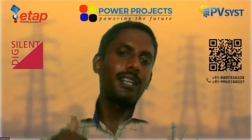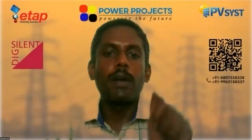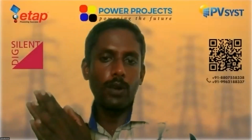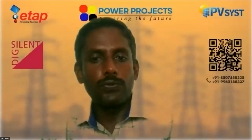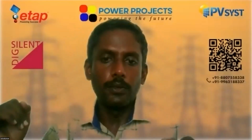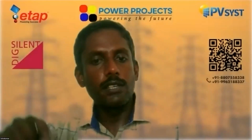If you take conventional generators like diesel, thermal, hydro, etc., conventional physical generators, they will typically inject 4 per unit as short circuit current. But if you take solar inverters, they will inject 1.1 per unit as short circuit current, because this is a power electronic device and contributes only 1.1 per unit. And that too, if there is a close fault, the inverter does not have low voltage ride-through capability, so in that case the inverter itself will drop.